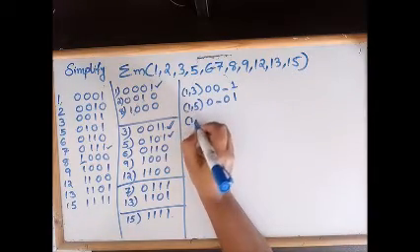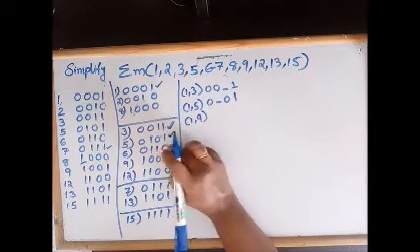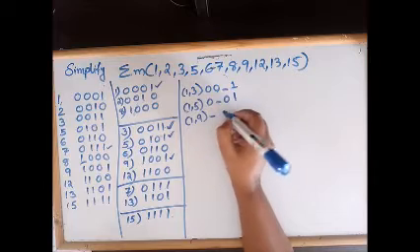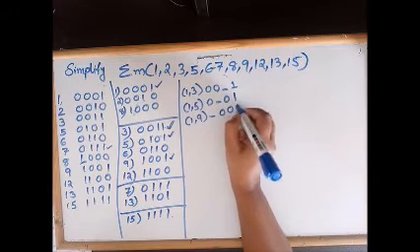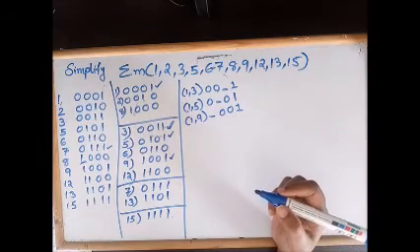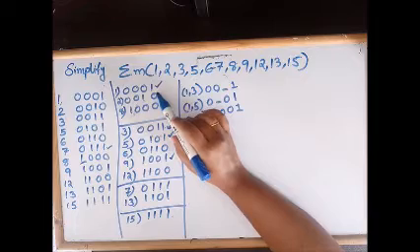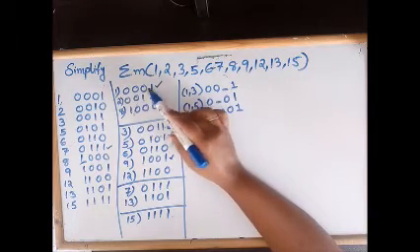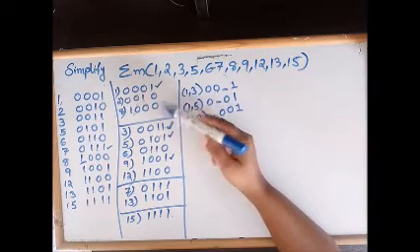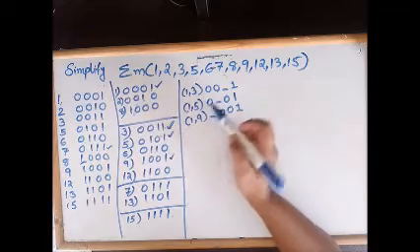So I am combining 1 and 9. How will we combine? Only the MSB changes, all others are the same. Okay, then identify the next combination. Now we can consider the second, that is 0 0 1, with 12. When you combine, there is more than one bit difference, so we cannot combine.